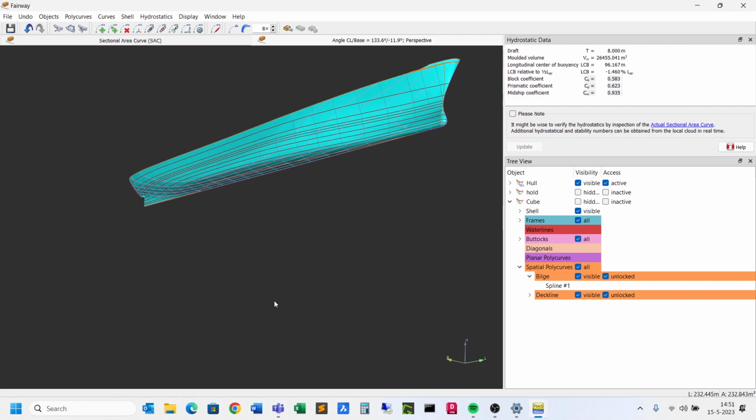So why your question, if I may ask? Pipe, when it's closed, I cannot create one surface. No, you need two surfaces for that. Yeah, four, if you want to make the end caps as well. A circular pipe is not by nature impossible. Actually, it would be difficult because the Kunz patch that we start out the NURBS transformation with will have two identical sides. So there will be nothing left of your Kunz patch, basically. And defining the contour would be difficult because you have two identical curves as a boundary. So it's more like an administrative problem than a real problem.